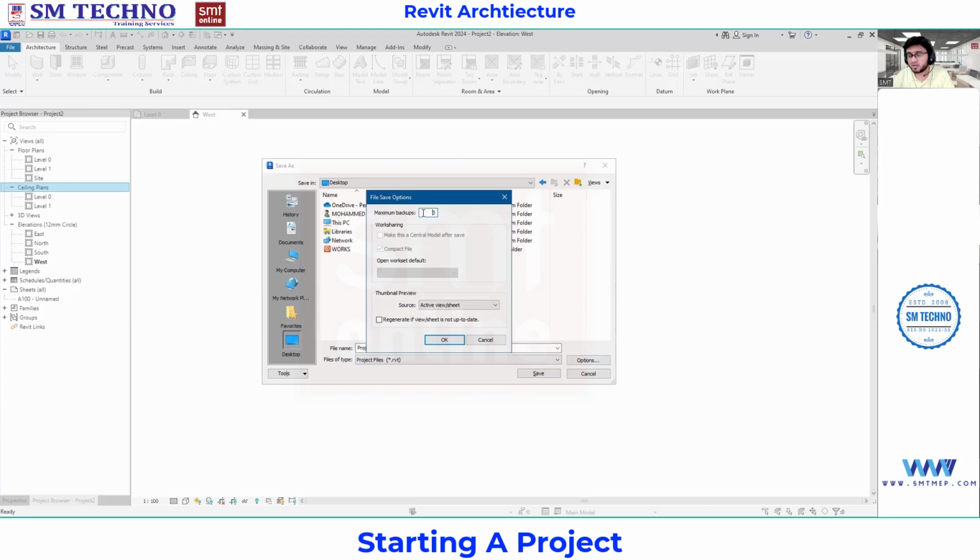That BAK file will be a backup file for you whenever there is any kind of interruption or shutdown of your software. So here also in Revit, we are going to find an option of maximum number of backups. Whenever you press Ctrl+S, it will save and create a new backup. So like that, I have given an option of 3, like maximum 3 backups will be there along with my main file.